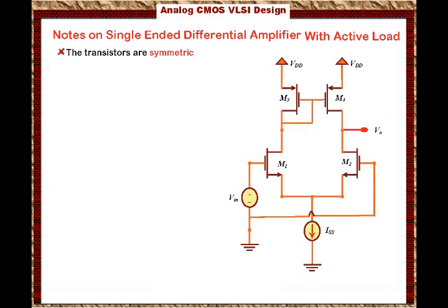Because remember that the bottom transistors M1 and M2 are differential amplifier transistors, which means that the same DC current has to go through both of them such that GM1 and GM2 are the same. The same AC current flowing from M1 will flow through M2, right? So this is by symmetry of the differential amplifier. This symmetry is required for the differential amplifier.